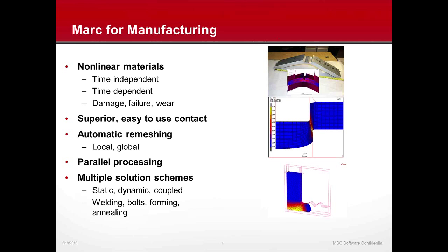Marc does offer a wide range of plastic material formulations to simulate the response of metals and non-metals alike. It supports isotropic, kinematic, and combined work hardening, and also numerous yield criteria ranging from von Mises to anisotropic Hill criterion, Barlat model, exponential cap, just to name a few.